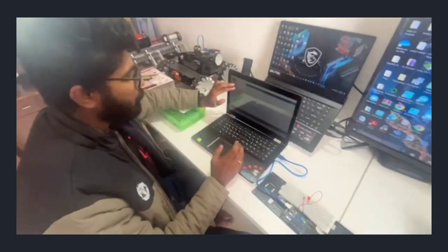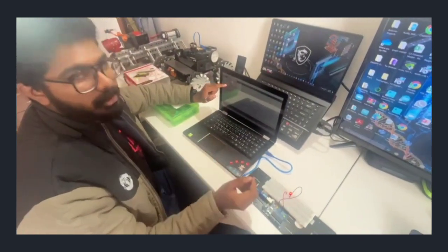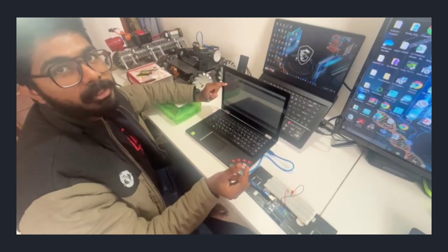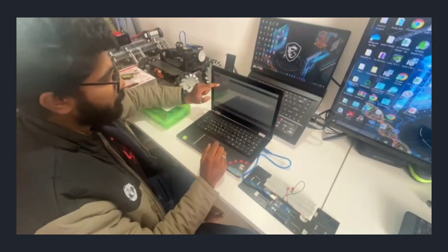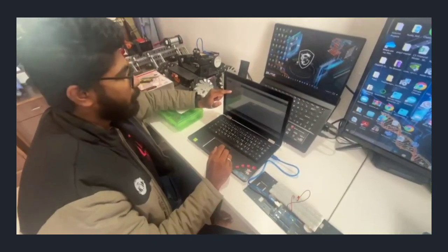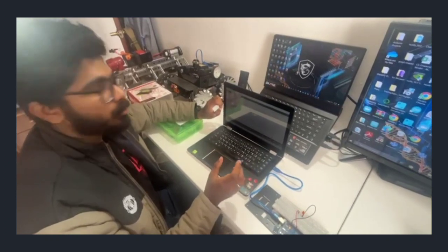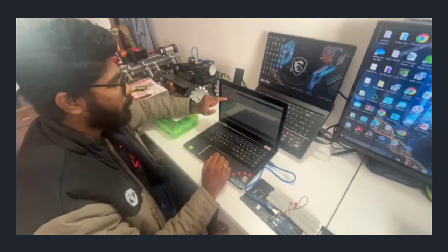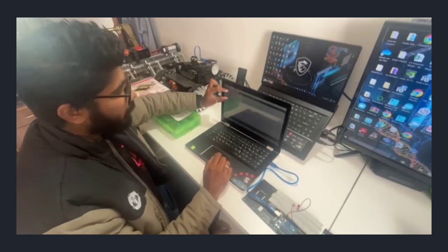Since Morse code is dot and dash, I have declared the dots as an integer because we need the delay time to be in solid integer numbers. And the dash is also given as an integer. And we need to have a break after the message is sent, so we are using a 1 second gap with the name long wait, which is also an integer data type. So the declaration is done.